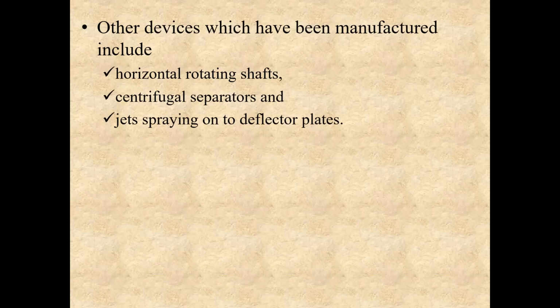Also, vinegar is a food product, so chemical antifoams are not desirable. So a mechanical foam breaker is incorporated into the fermenters or vessels which are used for vinegar production or fermentation. So this was all about monitoring and control of foam.